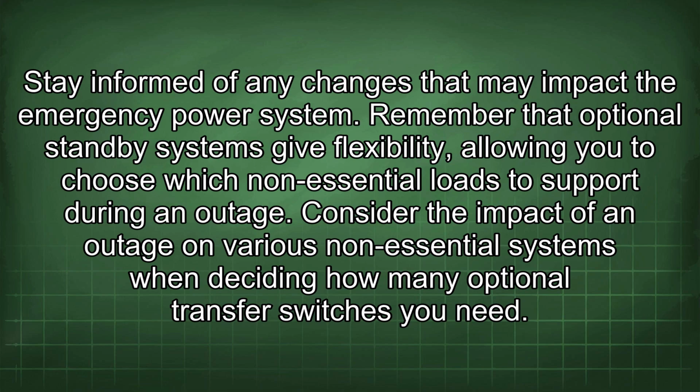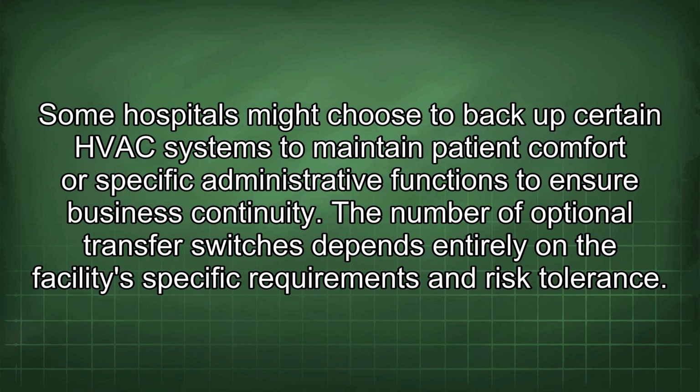Remember that optional standby systems give flexibility, allowing you to choose which non-essential loads to support during an outage. Consider the impact of an outage on various non-essential systems when deciding how many optional transfer switches you need. Some hospitals might choose to back up certain HVAC systems to maintain patient comfort or specific administrative functions to ensure business continuity. The number of optional transfer switches depends entirely on the facility's specific requirements and risk tolerance.